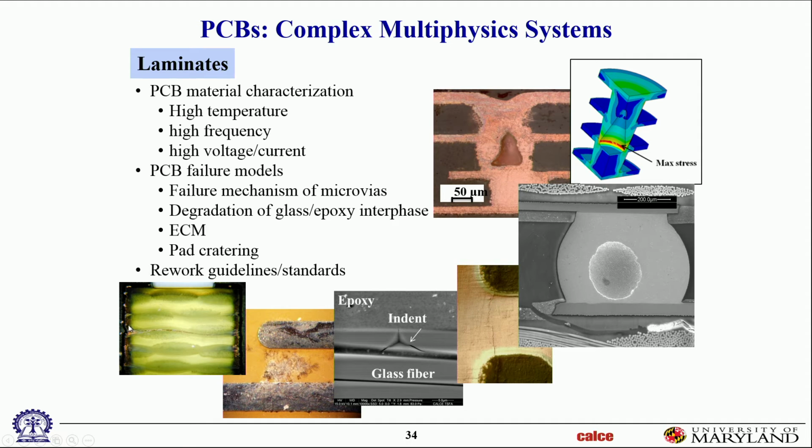This is the surface, and this is a cross-section. These things you're seeing are cross-sections of the glass fabric in the printed circuit card, and copper filaments form through them because the glass fiber debonds from the matrix. This is some testing we were doing to look at the debonding strength. Once it debonds, moisture gets in, and then the copper migrates from one metallization to another.